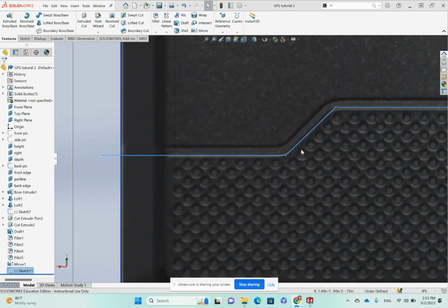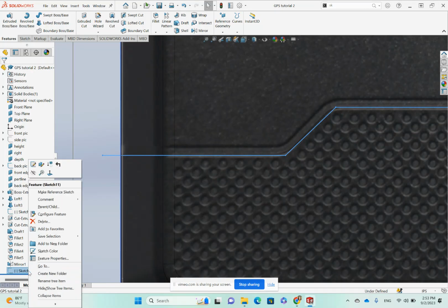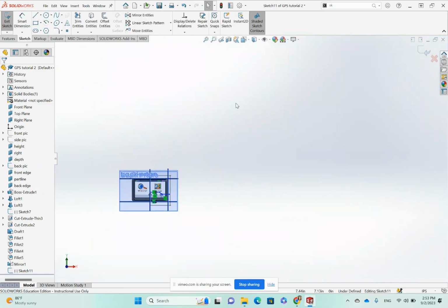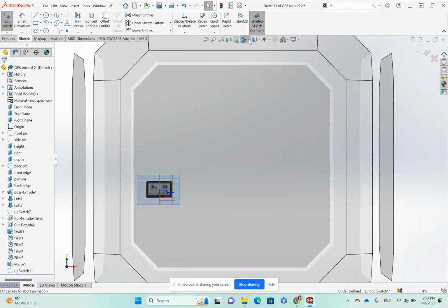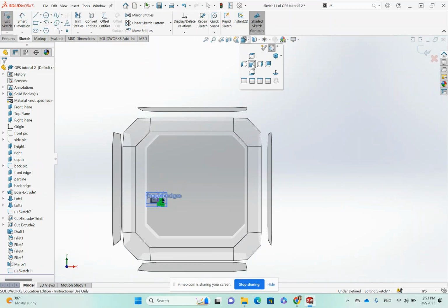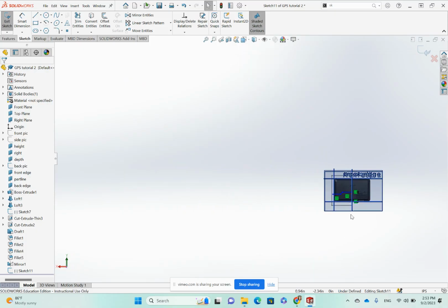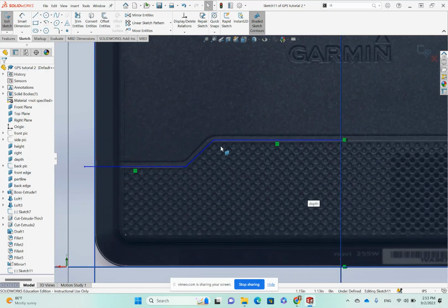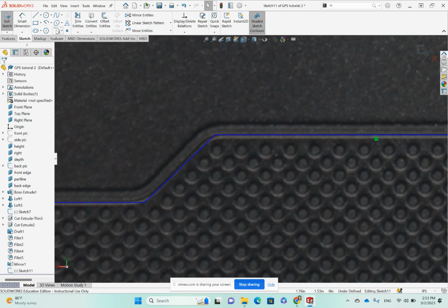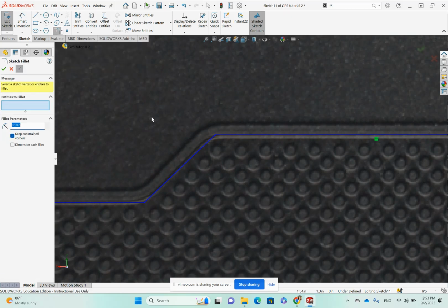All right, we were close with this line, but we actually want to curve it to match this drawing here. So in order to do that, I'm going back over the sketch. I'm going to right click on the sketch and I will pick this top left icon that says edit sketch. Okay, I probably need to change some setting on my computer, but don't forget if it flips around, do this normal to.